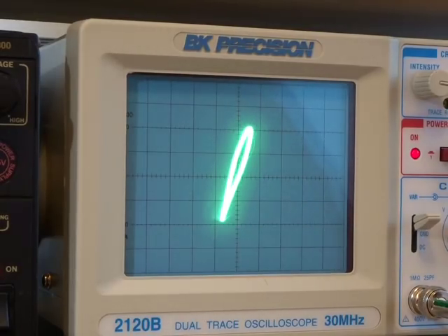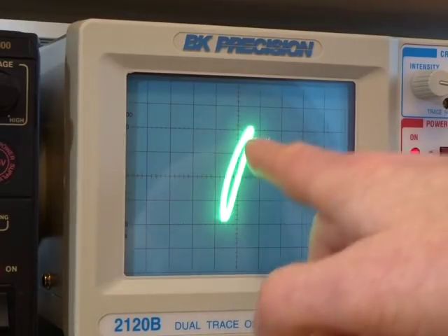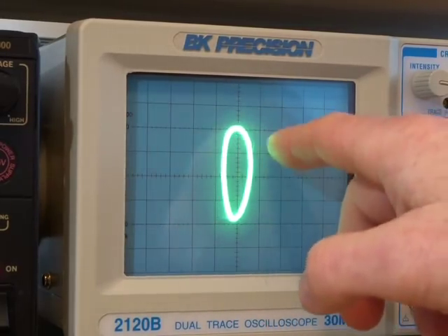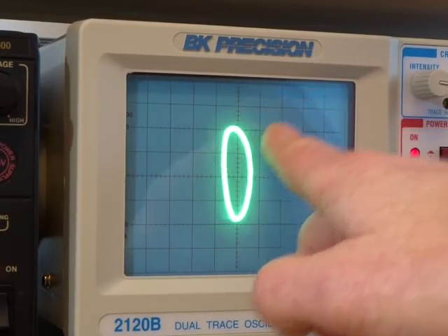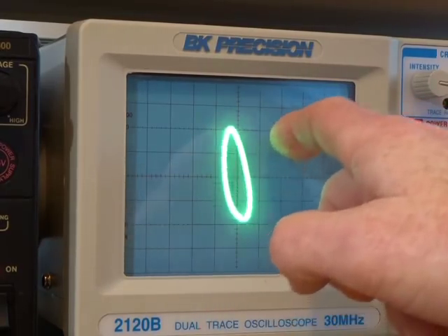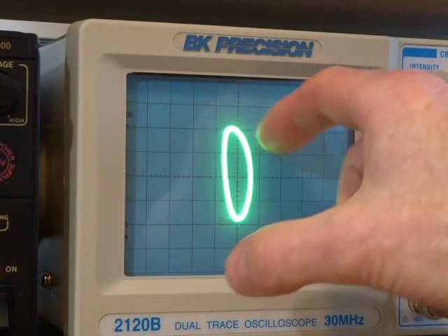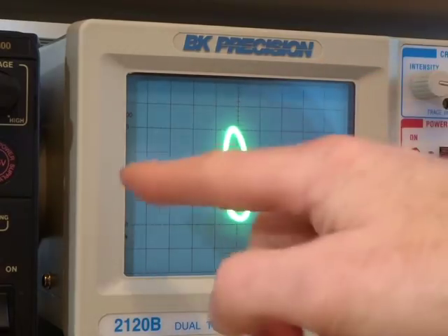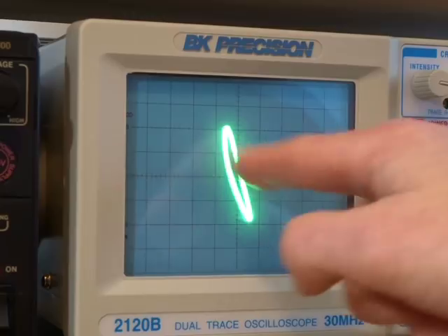Now if I get the frequency to be essentially the same, I'm going to create some symbols here. Depending on which way it's facing, a diagonal line in this direction here would be 0 degrees. A full circle there is either going to be 90 degrees or 270 degrees phase difference between those two frequencies, moving through to 360 and 180 and the like.